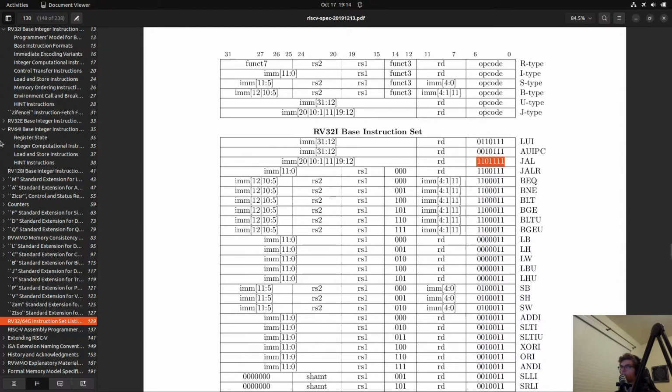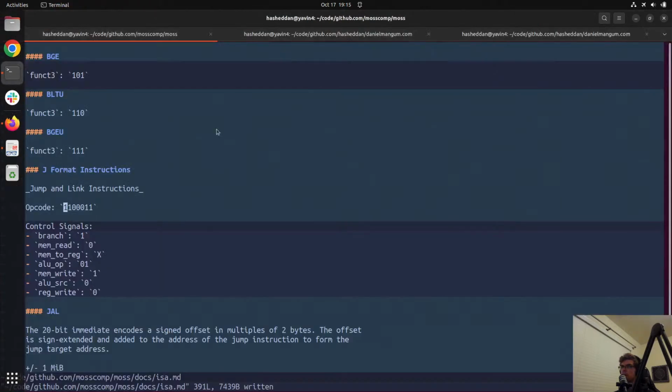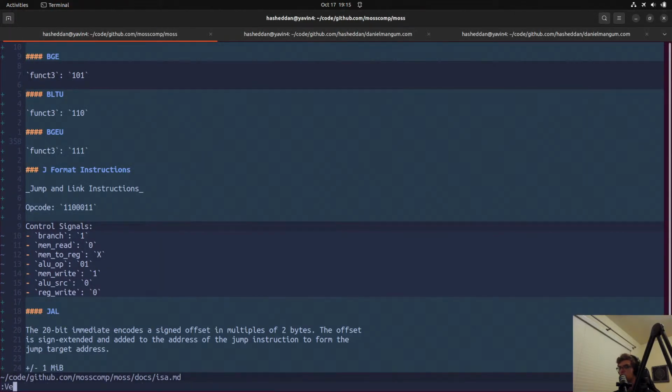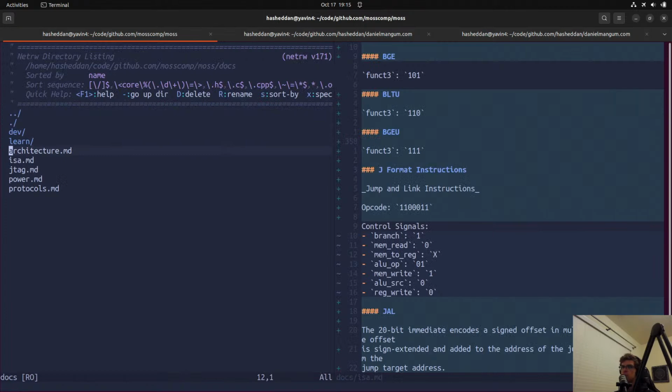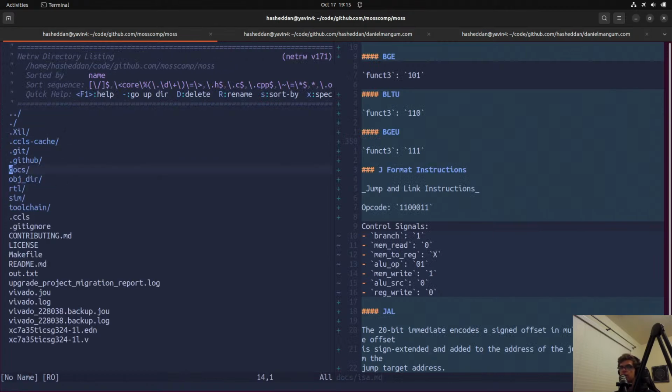Okay, cool. As a reminder, the two least significant bits of all of our opcodes are always 1 1, which we saw when we were looking at decoding. We can just use 5 bits, right, because the lowest 2 bits are always the same.